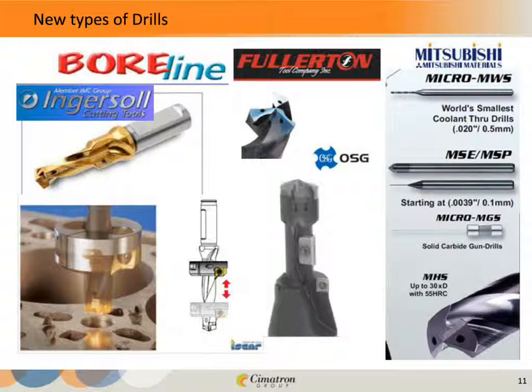And of course, with the through the spindle coolant, we don't do any pecking, which is kind of what this presentation surrounds, the ability to just blast through steel without doing any kind of pecking. Underneath that, there's a picture of a chamfer ring being mounted to a drill, and I know this is more of a production type application, and most of my customers are mold shops and die shops, but I think that today the line is really blurring between production machining and one-off machining. So even the practices that we would have said, well, that's really a production tool, I think is having more and more of a place in job shops and mold shops.